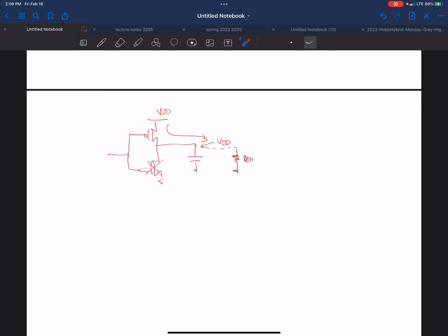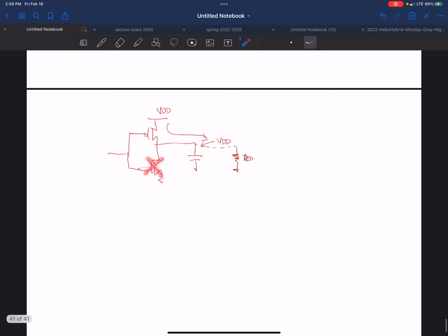But as you guys saw, hopefully, or will see in your projects, if you're not worrying about timing, you weren't picking the size of your transistors, or you'll see, you don't have to pick the size of your transistors. Your output, if you give it enough time, will always go to VDD. Because this guy's off. Again, if this NMOS was on somehow, even a little bit, you'd get a voltage divider action, and you wouldn't go all the way up to the supply. And vice versa. If the PMOS didn't turn off and the NMOS was trying to drive that guy to ground, the output wouldn't go all the way to ground. You'd get some voltage divider action.